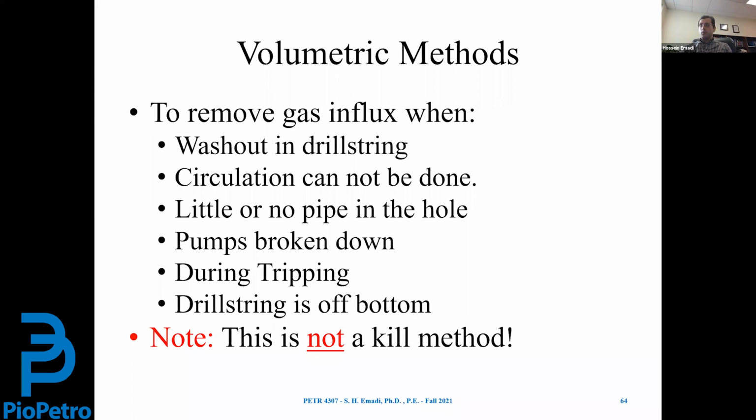In this way: when 1 gallon of salt water enters the wellbore, a downhole condition, it stays there. Or if it moves due to the density difference, it moves very slowly. And since it's incompressible, the volume does not change. So 1 gallon of salt water at the bottom of the wellbore will be roughly equal to 1 gallon right at